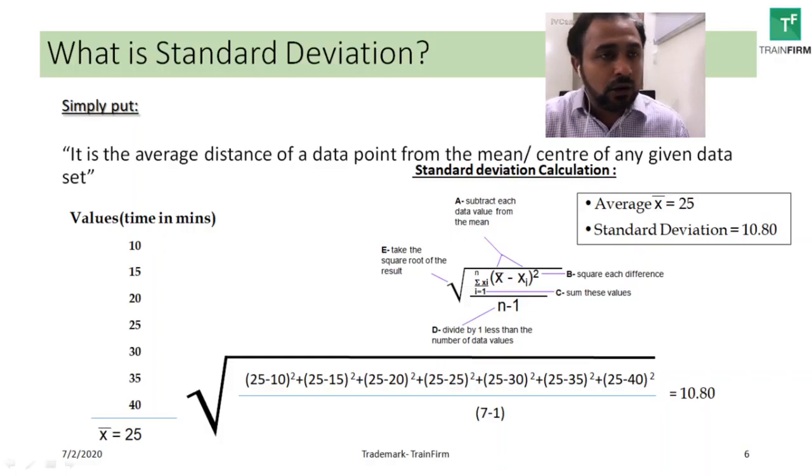So it's lower the better. If I have got lower standard deviation, my process is leaner and it is actually operating closer to my target or probably to my mean, right? So that's my intent of driving Six Sigma, to reduce this standard deviation so that I have a leaner process which has a lesser number of defects and operates always closer to the target. And that's the methodology, okay?